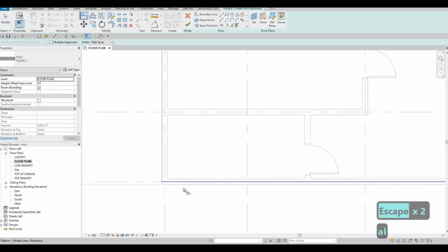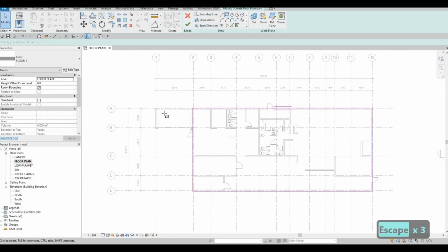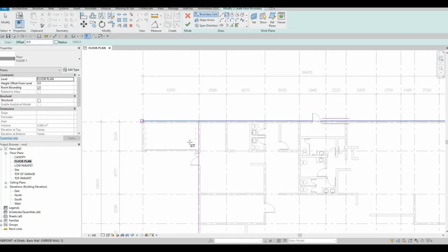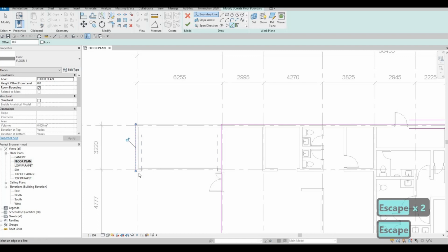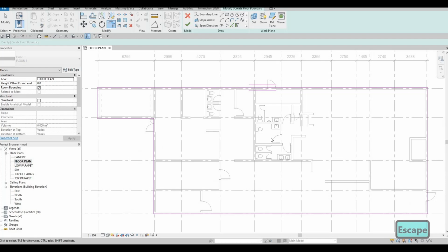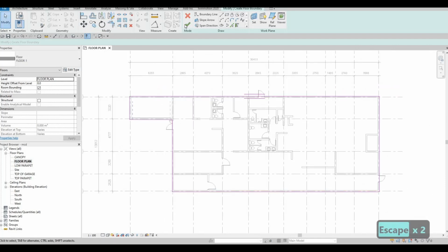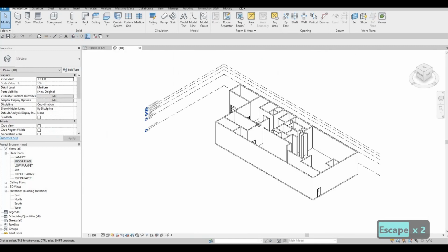So that's a line right there. And then another rectangle, or we don't need to click on that. We could just click on the pick line. And then here, TR, trim and extend, and then trim and extend right here. And that will be good. Click finish. And then we have our flooring.